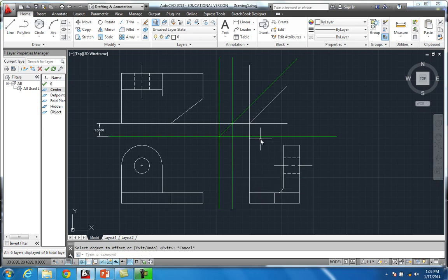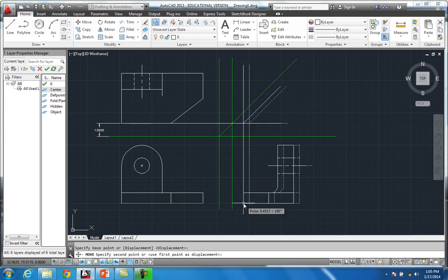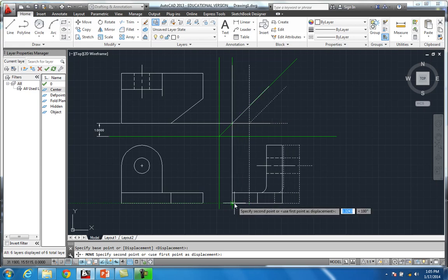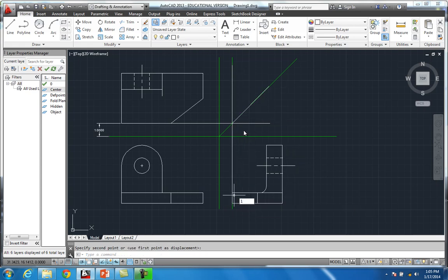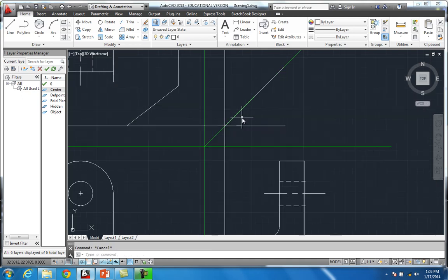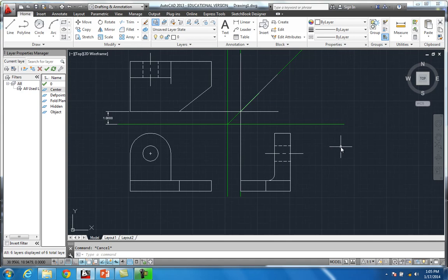And what I want to do is bring this right side view over 1 inch to where it's exactly 1 inch, because we're working in depth. Okay? So I want to move it, and you're going to see something. You see this miter line coming right off that fold plane? You're going to see something right here. And I want to bring it over 1 inch. Or actually, I can just come over and just touch it. Check that out. Y'all see that? That miter line that I had with this one over that was offset, when I brought it over 1 inch, it all lines right up. So that's what I'm saying.